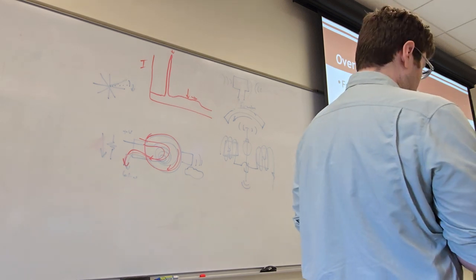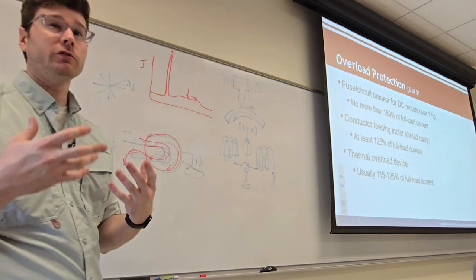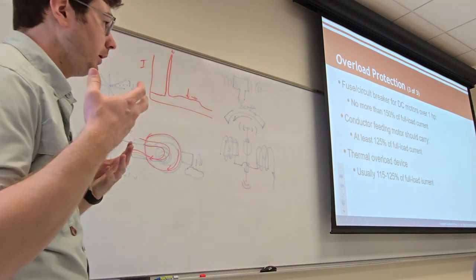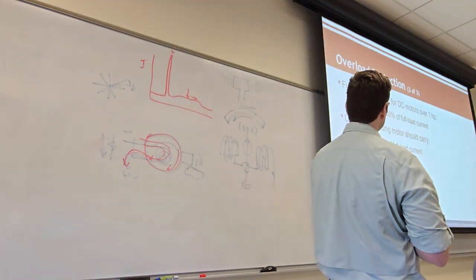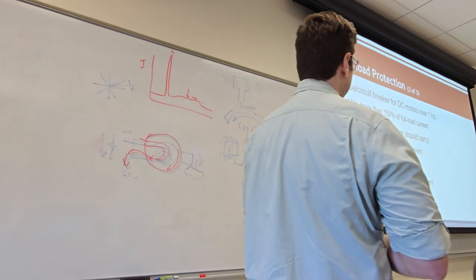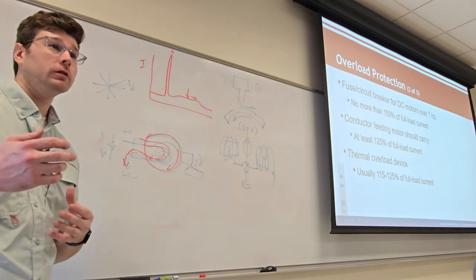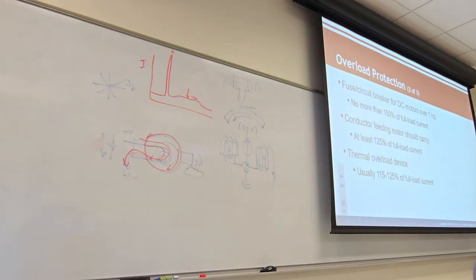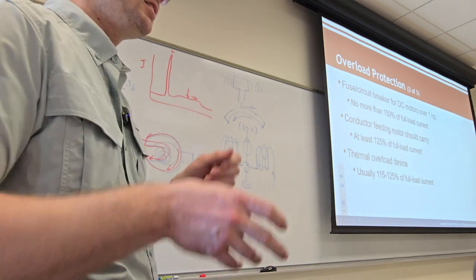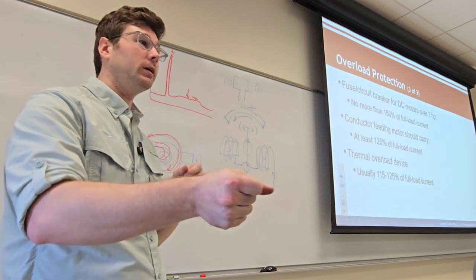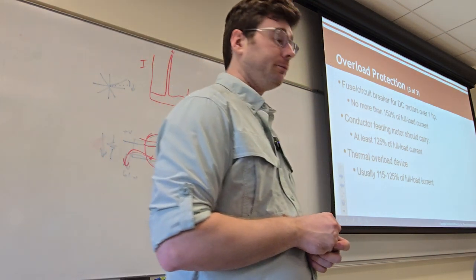When we're talking about protection to put on a motor, that's usually something that the person is responsible for buying. You buy a motor, and then you have to figure out how big of a fuse to put on the thing, okay? These are a couple of rules of thumb for those devices. The reason that they're rated differently is that they'll trip differently. Some fuses are slow blow. It takes a while running at that energy before it'll trip. Others are testier, more sensitive. They'll trip more easily, or they won't restore as easily. So these are some good rules of thumb for that.